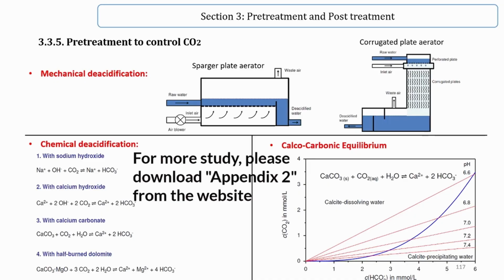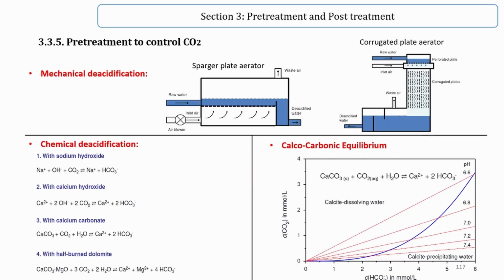If there is no calcium carbonate available for the reaction with carbon dioxide, or if the contact time between water and carbonate is too short, the seepage water and groundwater cannot reach the state of calcocarbonate equilibrium. As a consequence, the water contains a carbon dioxide excess, which gives the water an aggressive or corrosive character.